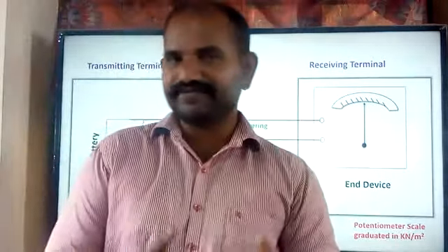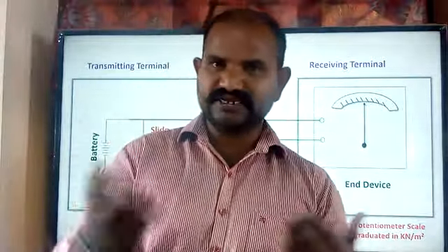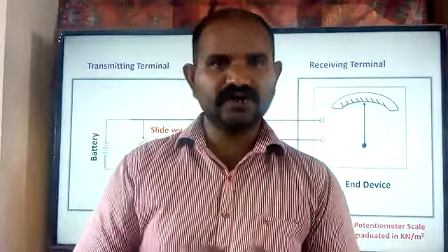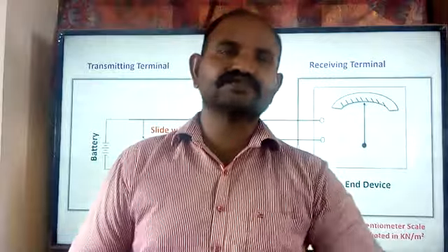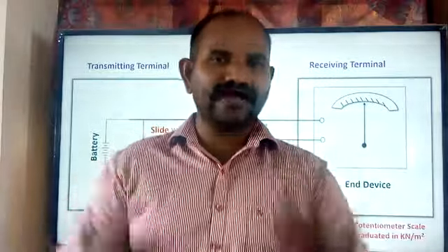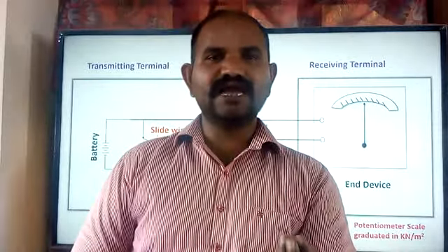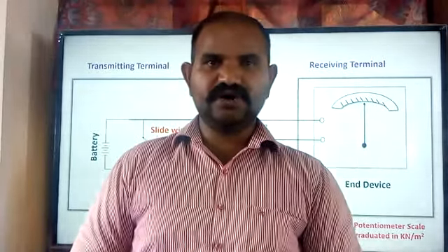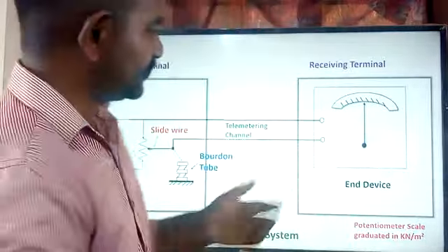When we are sending the information, we can't send it in the voltage format only, but obviously there is a current which is transmitted along with the voltage. What is the current which we are transmitting along the voltage? It is not going to be in the high current ranges. It is in the small currents. Milliamperes of current is more than enough to transmit the information from the transmitter to the receiver. That's one of the advantages of using the voltage telemetry system.